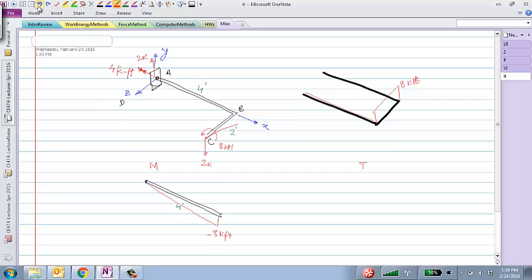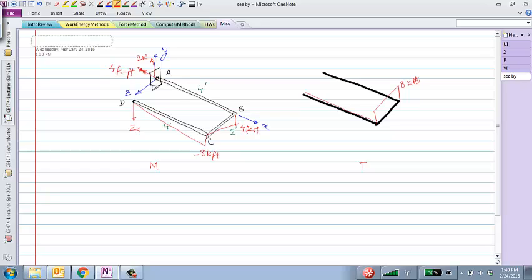So it will just be a negative bending moment out here. And maybe what I do is I'll undo the change that I did here so that I can go back to that. And now I know that there's a negative bending moment of 4 kip feet here. That negative 4 kip feet goes where? It becomes torsion in the leg AB, right? So if you look at the leg BC and AB, the leg BC is coming under bending like that, and it's going to create a torsion on the leg AB. So that torsion will be in the amount of 4 kip feet in this direction.